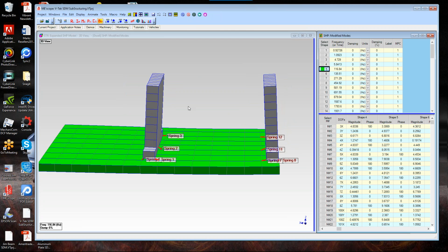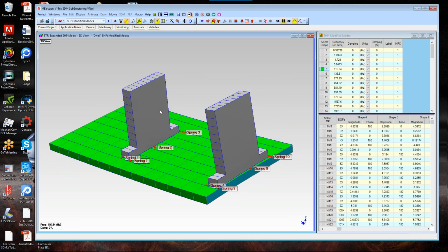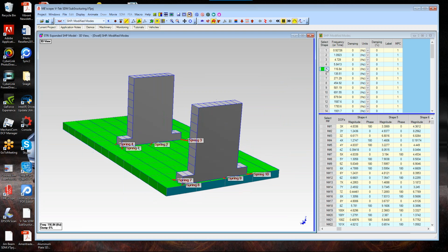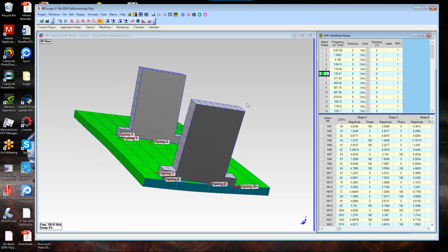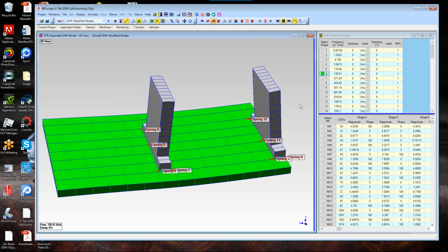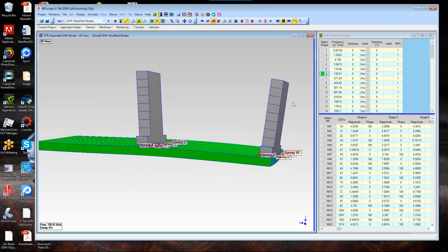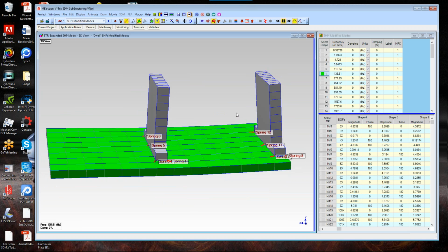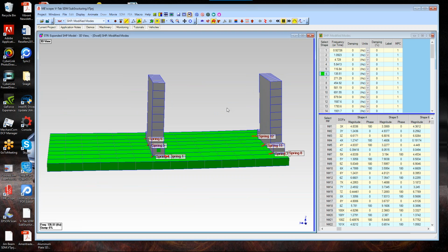Okay, here's mode number 5. Now we're starting to see a little flexure. So we don't have, in this case, necessarily 6 rigid body modes. We got a little bit of flexure here. And you can see the frequency is 116 Hertz. There's another mode that, we expect the first 6 modes to look like rigid body, but we're seeing a little bit of flex of the bottom plate and a little bit of rocking of the bearing blocks on the bottom plate.